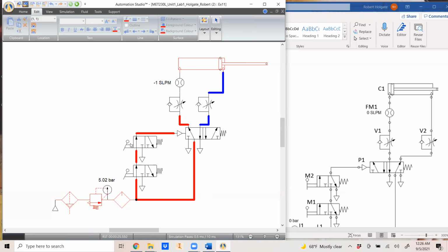But either one, I can stop either one, and the impulse value will be lost, but the spring return will then be able to force it over. Okay, so M1 has to be actuated and M2 has to be actuated, and they have to be constant pressure on this pneumatic impulse because it does not stay put just like the previous one did. The spring return will bring it back.